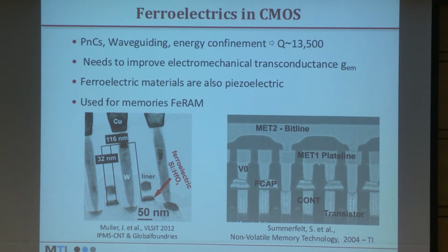Well, we were looking for piezoelectric materials, and these are starting to appear in CMOS technologies. They are used to make FeRAMs, in the form of ferroelectric materials. So we were looking at GlobalFoundries technology here. They have a ferroelectric layer inserted in their gate stack, so we were considering that. And we are also working with TI on this, on their technology, where they have specific FE-cap devices used independently. So we are trying to use either of these technologies now to enhance the amplitude of the transfer function, which will enable us to get low power oscillators.